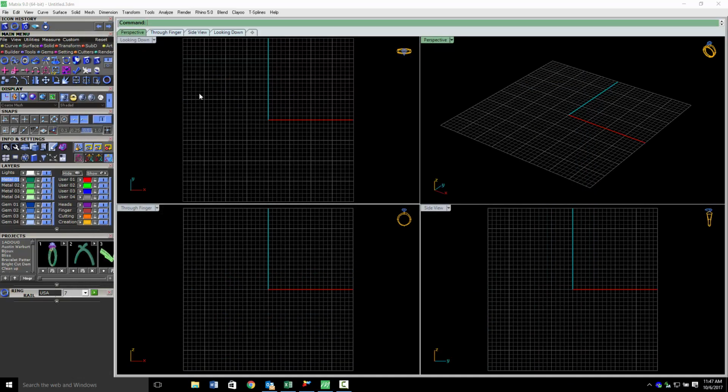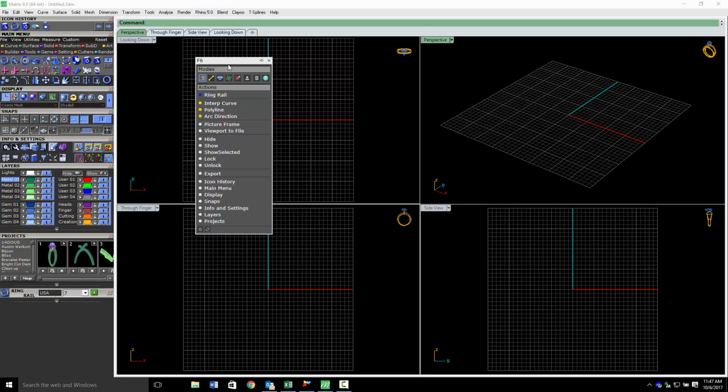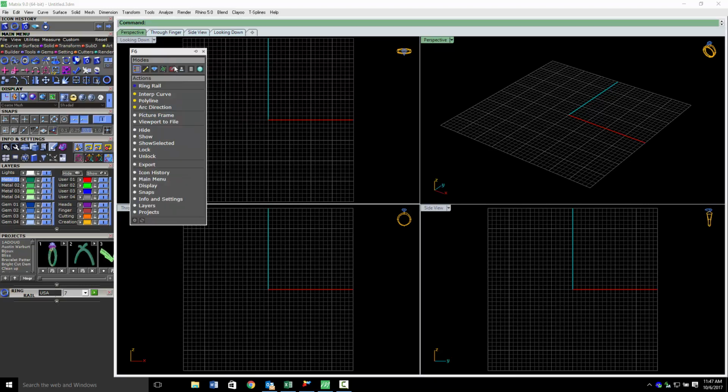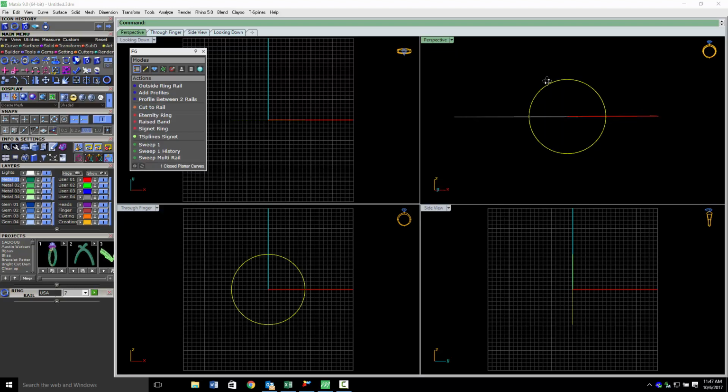Another thing that we added in to some of the later versions is a tool that's always been here, which is the F6 key, but we now have the ability to lock this F6 key out onto the screen. Before, every time you do something, you'd have to go back and grab it, and change it, and hit F6 again. We no longer have to do that. We simply go in, select whatever tool we want. If I want to choose a finger size 7, I'll drop this out there just like that.